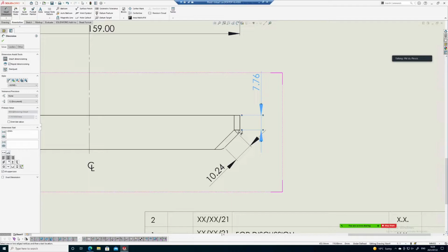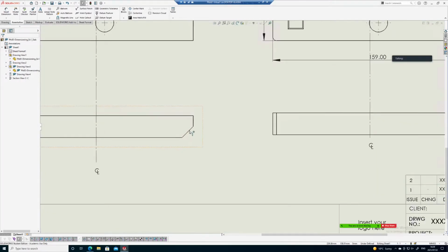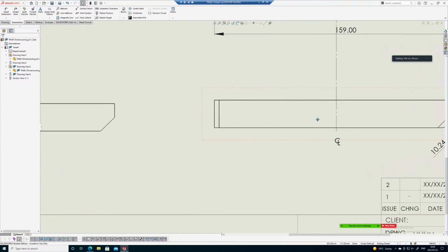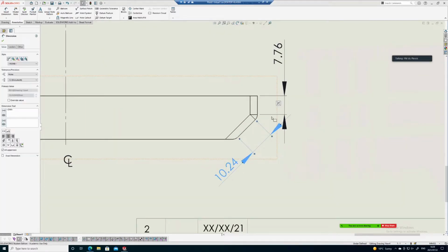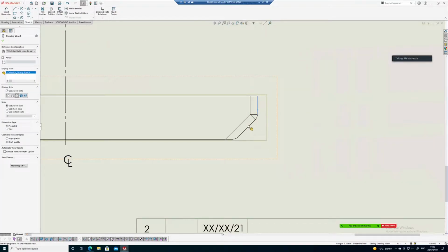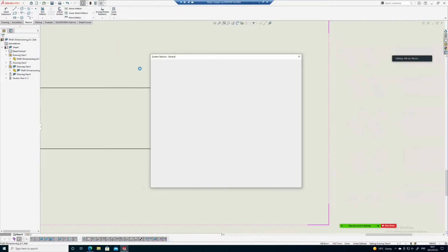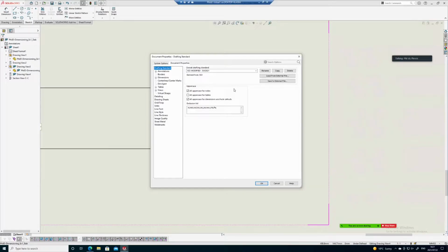This is going back to my point: you have to be able to picture this item here as essentially this item, and then you add the radii in. So remember, most of you should remember this, the way in which we put in a virtual sharp is that you select the two lines by holding the shift button down, or was it control, I never remember, and then you put in a virtual sharp. Right, so the virtual sharp at the moment is this little shape. I will change that when I give you the question.